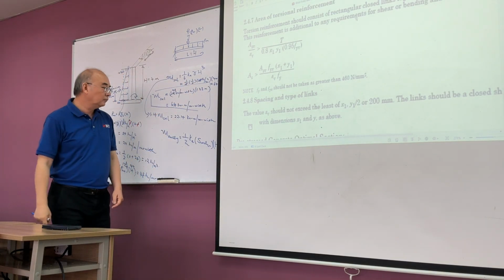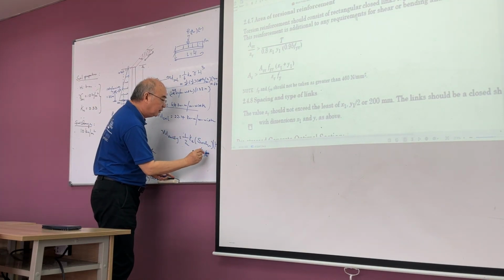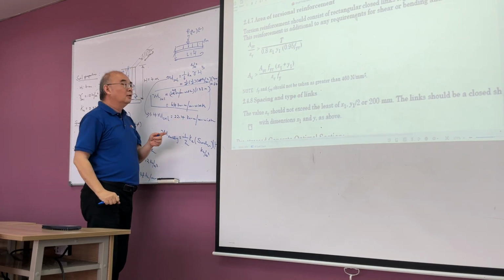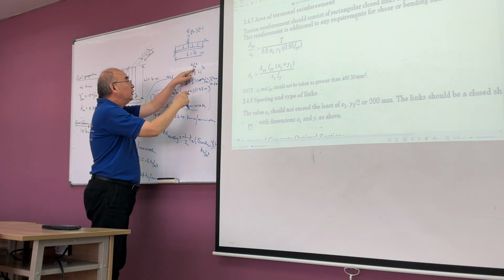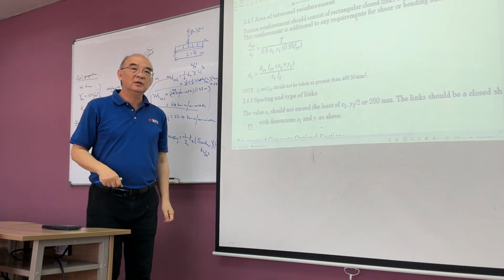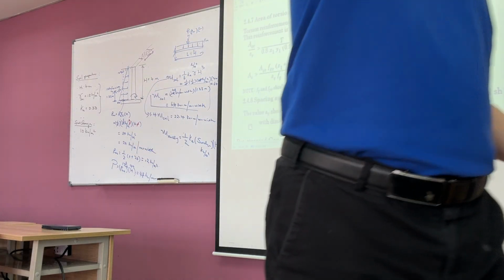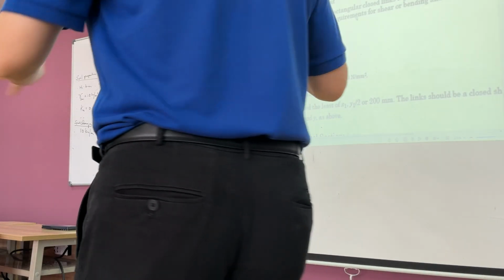Alright? Because why here is H squared? Because the surcharge units is kilonewton per meter squared. This one, the gamma, is kilonewton per meter cube. Okay? So meter square, H squared cancel out. Meter cube, H cube cancel out. Understand? Okay, so yeah, what is moment due to the surcharge? 1/2 of Ka surcharge H squared. Okay, alright, just remember this, because then you have the design moment ready.